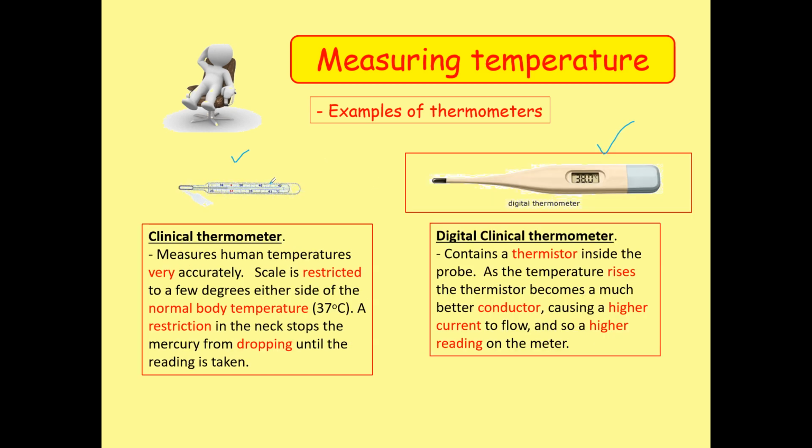Then we have the lab-based thermometer, which looks just like this one, right? We even have a digital thermometer in the lab at the moment, which has a wire instead of this fixed one. This sensor, or the RTD, I just said, resistance thermometry, is actually connected to this digital module using a wire. This is a fixed one. The one I'm using has a long wire, so it gives a digital reading on this gauge. We can just read it out.